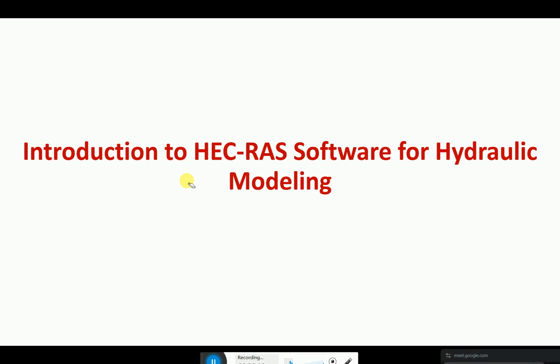The second one is channel routing. Channel routing studies the movement of flood water through rivers and canals, used for rivers, streams and drainage channels. Popular methods include the Muskingum method, Muskingum-Cunge method, and kinematic wave and diffusion wave methods. In this case, the Muskingum method is very popular in HEC-RAS. In HEC-HMS, it is the modified Puls method.